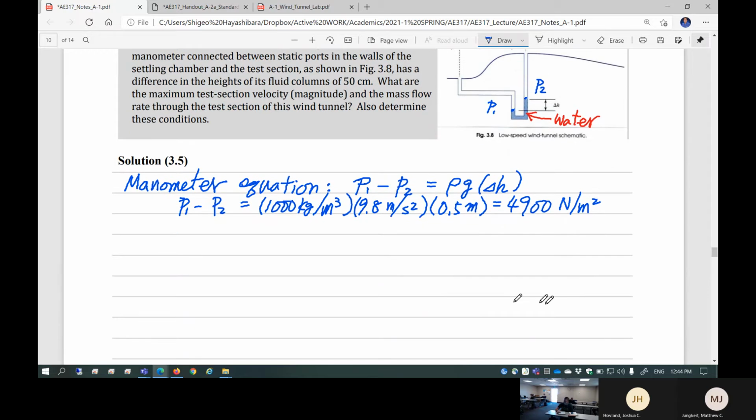So next step is, of course, P1 minus P2. What do you call that stuff? If it's a pitot-static probe, the pressure difference between the center tube and side port is called the dynamic pressure. In this case, it's not. So we are going to plug into the equation on the previous page.